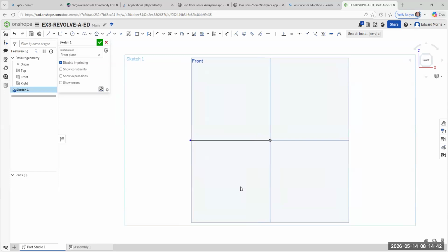Okay. Now, I'm going to draw another construction line that I'm eventually going to delete. But for right now, please go to line. And I'm going to start right here at this point. See this point right here? It will snap to it. Click and come up a little bit, and I want you to click and type in 0.5, enter, and then hit the escape button.